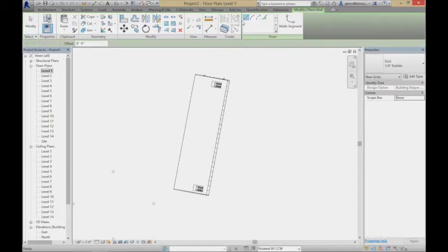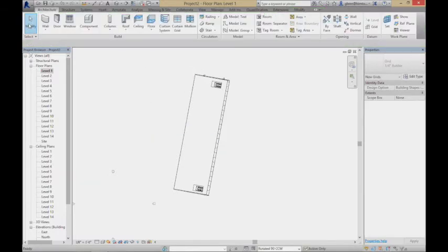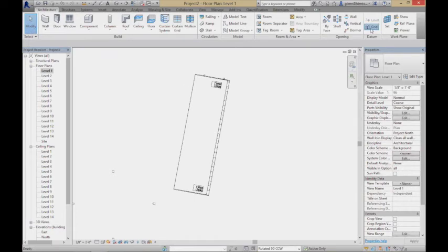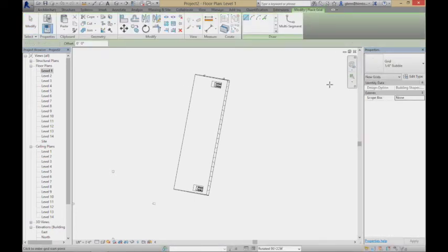So if I was a structural engineer looking at this, I might go ahead and put some structural grids in here. Getting it to line up perfectly is kind of hard. Let me approach it a little bit differently just so I can give you a better technique. One question you're going to think about is, when you put the grids in, are they going to be at the outer surface of the building or are they going to be inset just a little? Actually most people will inset them just a hair, so that the grids and all the columns are inside the surface of the glass.